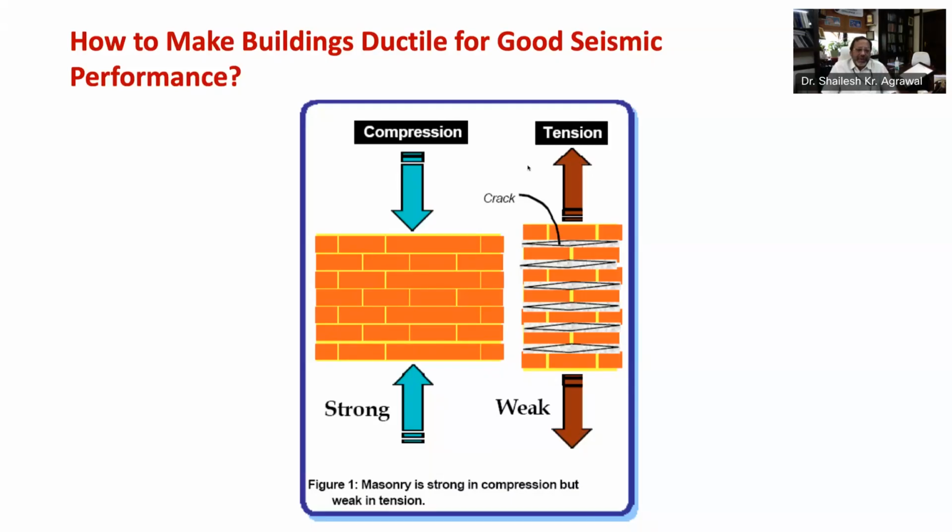Now, to impart ductility, steel is the material which is used in masonry and concrete buildings as reinforcement bars of diameter ranging from 6 mm to 40 mm. These reinforcing steel can carry both tensile and compressive loads. Moreover, steel is a ductile material. This important property of ductility enables steel bars to undergo large elongation, that is the displacement, before breaking.